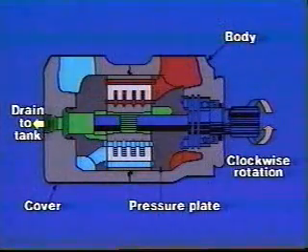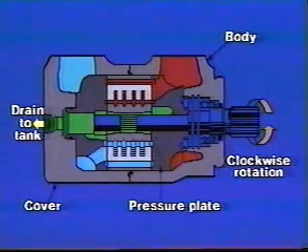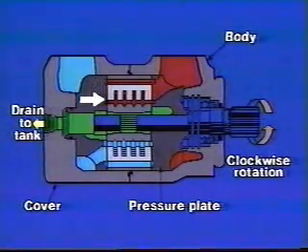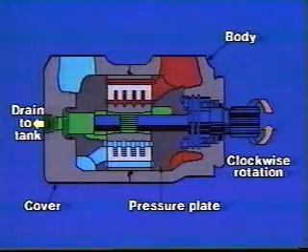Now, here is an illustration of a high-performance balanced vane motor. It operates at higher speeds and pressures. Like our intravane pump, it features a pre-assembled, pre-tested cartridge for speedy field replacement. We can see that high-pressure oil coming in at this port is directed to the top and bottom of the vane. On the discharge side, we see low pressure top and bottom. Thus, we're balancing out the pressures, top and bottom of the vanes, to reduce vane tip loading.